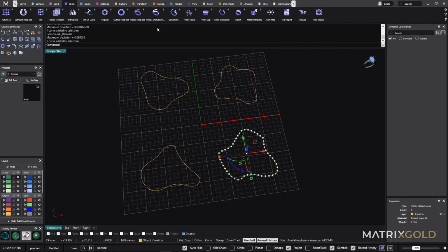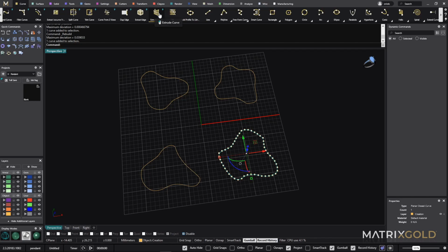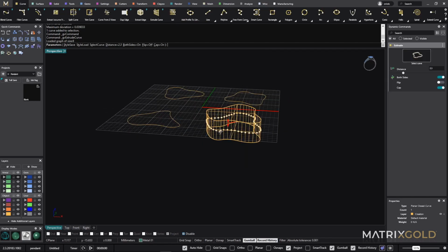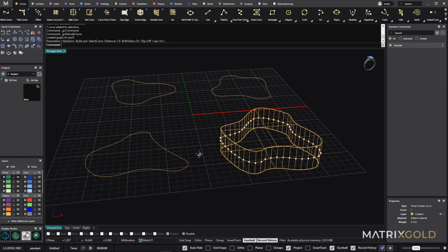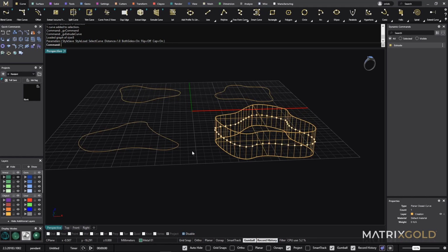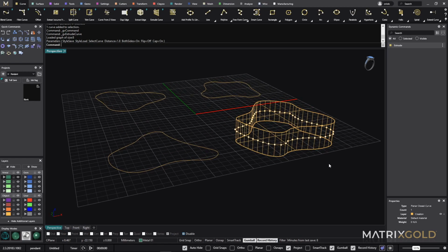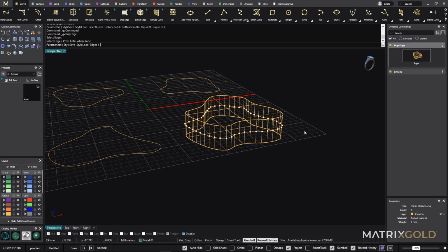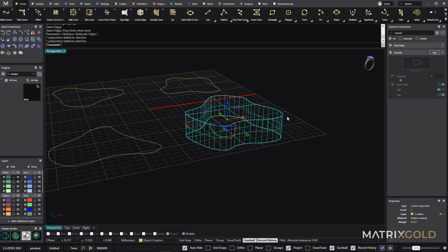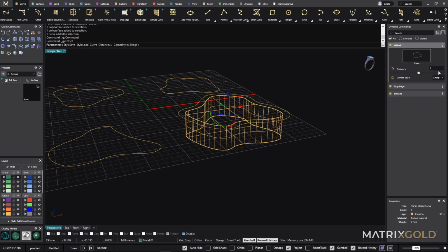Okay, let's start to do what I was looking for. So the first thing that I will do is just the extrude. We have it here in the curves tab, like this. It's okay. And then what I will do from here is just to extrude another curve. To do that, what I have to do is just first dupe the edge. The reason that I am doing it like this is because I want to keep it parametric, and once I finish that, you will understand why I do it like this. So now I will select the curve that I duplicated, that is that one, and I will get an offset. This will set up the width of my pendant. I want it to be 1.7.